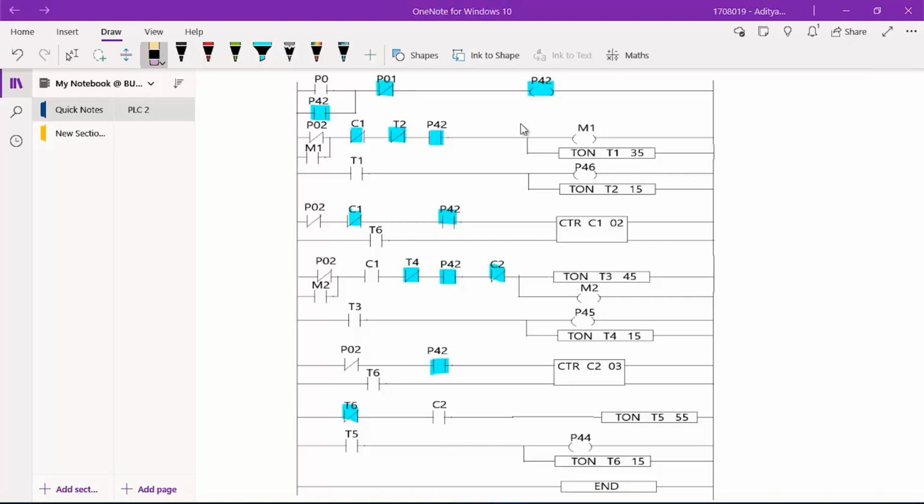So let's work this out. Suppose we have put one object onto the conveyor and it will get sensed by the sensor P2. I will quickly go through. Okay, all the P2 across the ladder logic diagram will receive the signal. This counter will count to 1. This counter will also count to 1. Here M1 will receive the signal, and the timer T1 will start receiving a continuous signal. Obviously, after some time, all the P2 will lose the signal, but it will keep the timer T1 running.